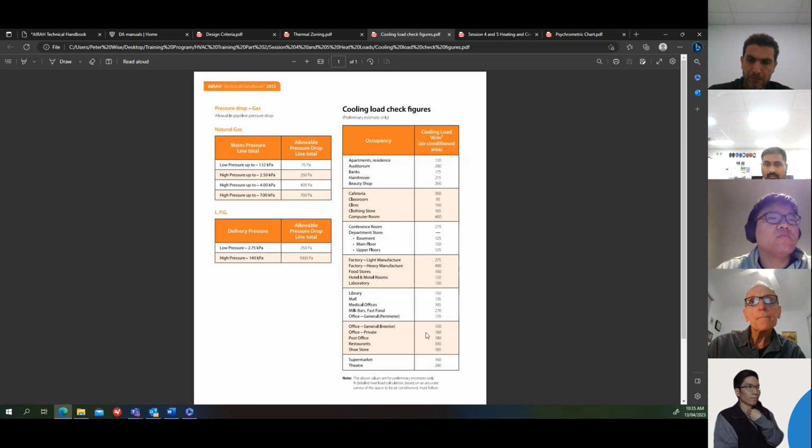But if you get something like 400 watts a square metre, something's wrong, which usually means you've got something wrong in your input. In the case of that resort, the young engineer had put in, I can't remember exactly what it was, like 100 watts a square metre for lights or something like that. We found that it was changed, and then we got the results we needed.